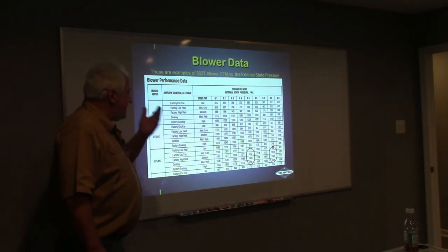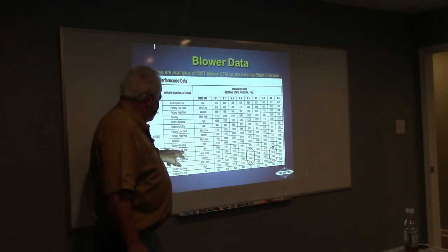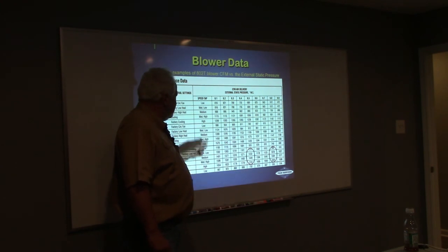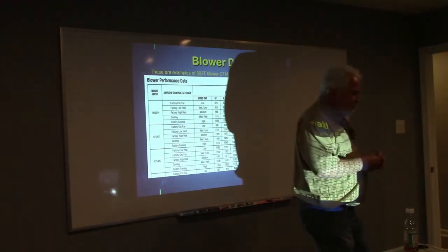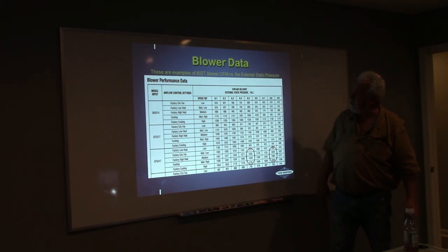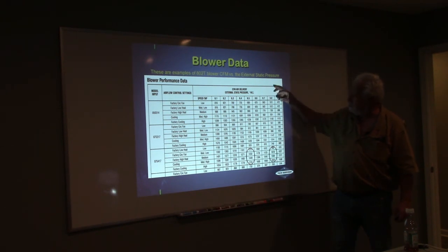So when we look at it now, okay, here's my model number. I'm looking at factory low, factory circulating fan, factory high heat, factory cooling. Okay, factory cooling right there. Look, it's on a high speed there. And we measured those two different furnaces. One of them was a 0.5 static, and the other one was a 0.8 static. This is off of that 802T blower. We've seen these out there. On this one, at that 0.5, I'm going to move 1741 CFM on this unit. This one over here, I'm going to do 1625.